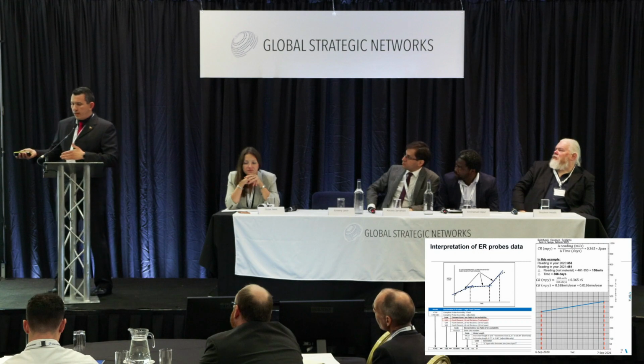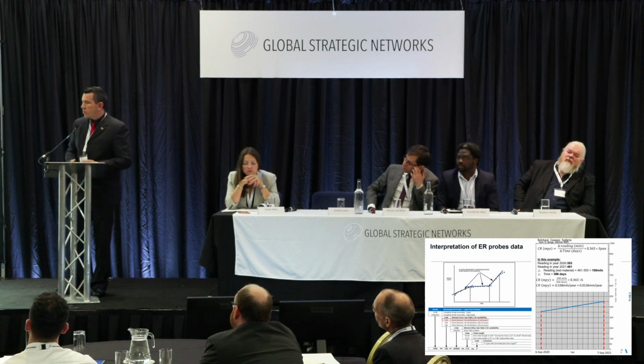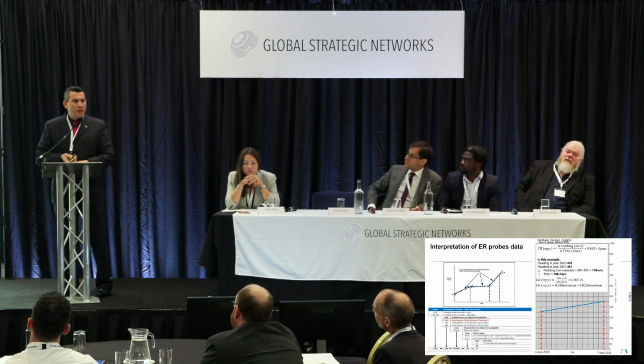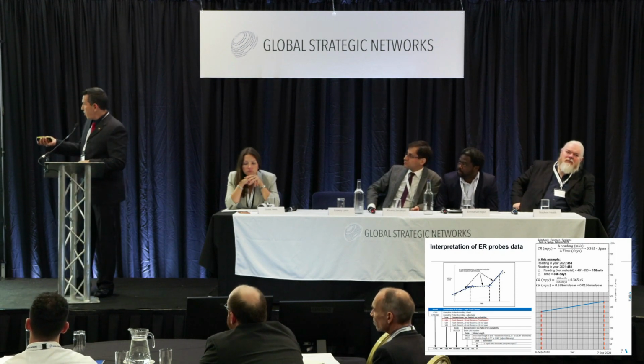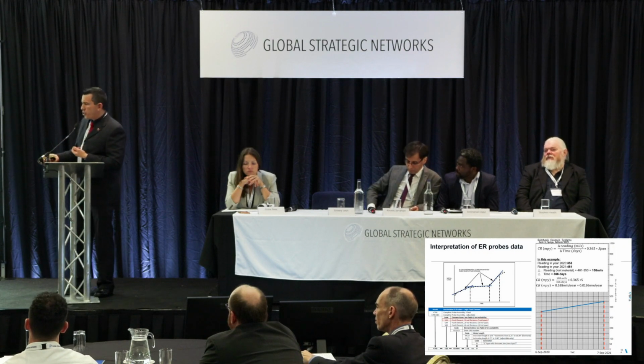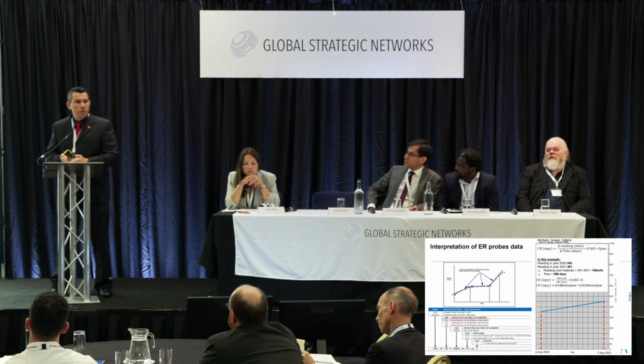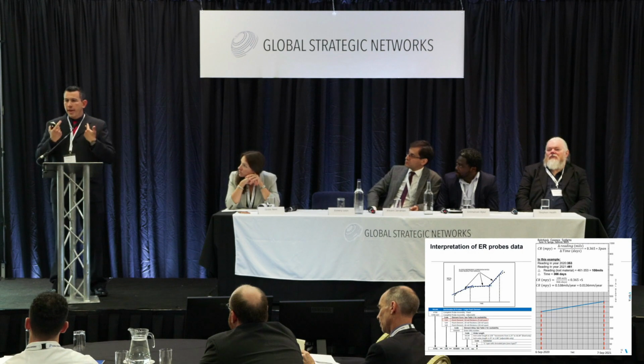And this is a real life example on how to calculate corrosion rate with corrosion probes. This is where things get complicated for some operators, because what we get from the handheld device that you saw earlier in the picture is a reading that is between 0 and 1,000. 1,000 because usually corrosion probes, the area that they have exposed is divided by 1,000 parts.